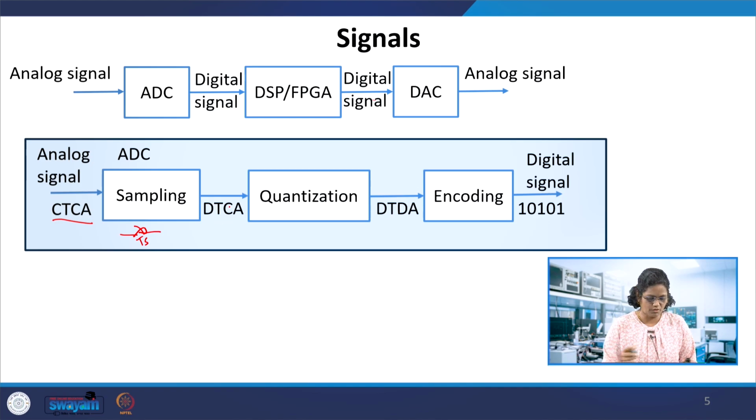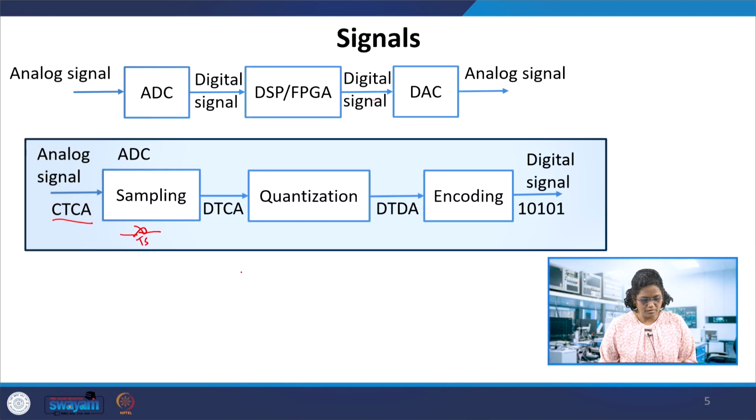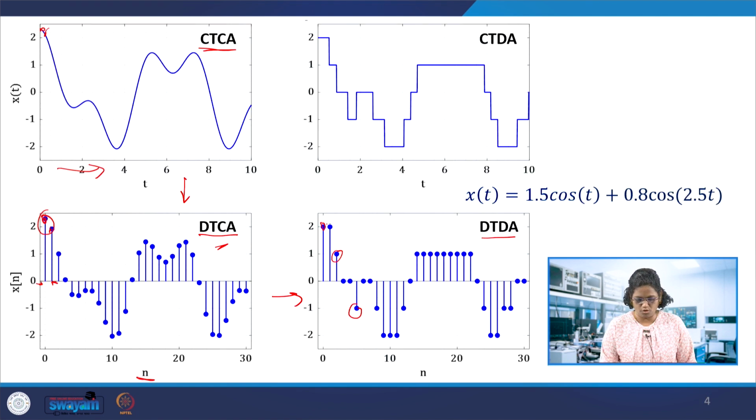So this is the signal which we had looked into here. The second one is the process of sampling, which is also called the impulse modulator. So after the sampling process, we get discrete in time and continuous in amplitude, and the quantization happens here. The quantizer output has values made to round off here.